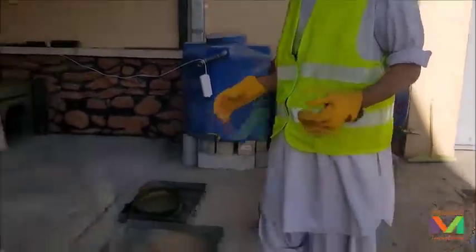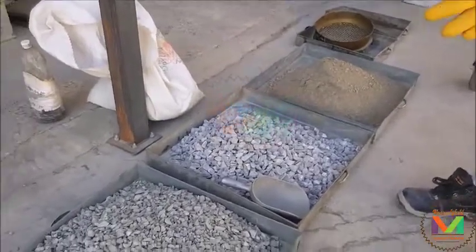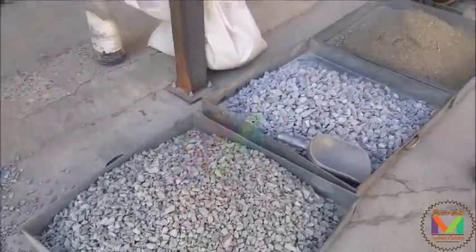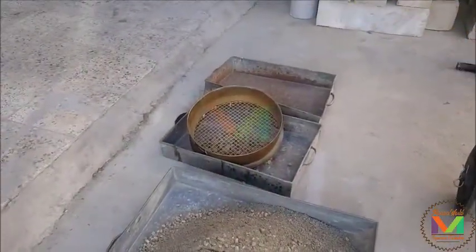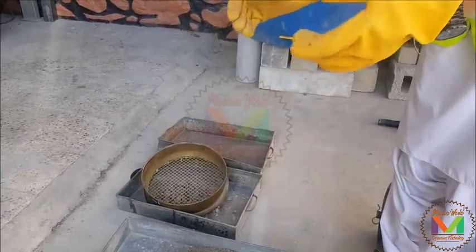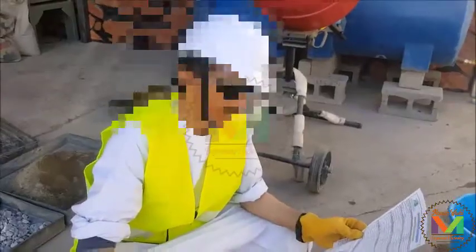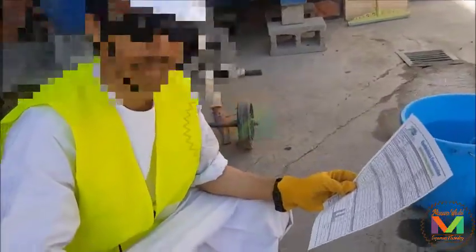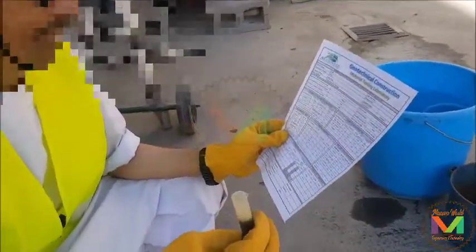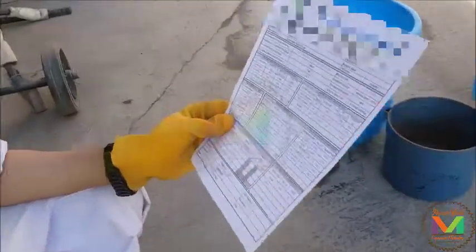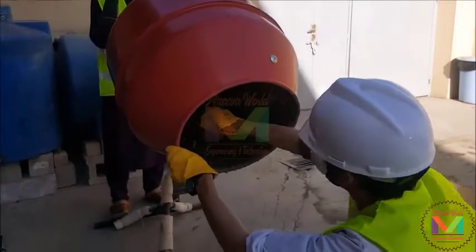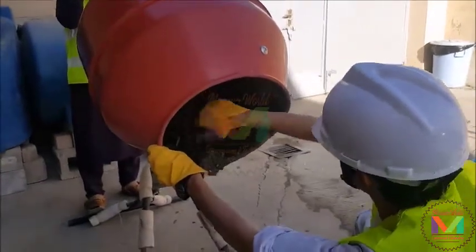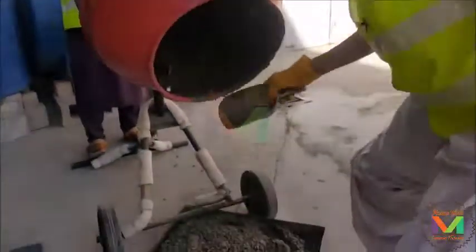As you can see, we have two kinds of coarse aggregate, and we have fine material, which we have already passed through the 3/8 inch sieve as well. According to C231 section 6, based on our batch weight, we have prepared the air entraining agent, 7.84 ml. Therefore, we will put it into our trial and mix it. As you can see, we have prepared our mix. It's done.